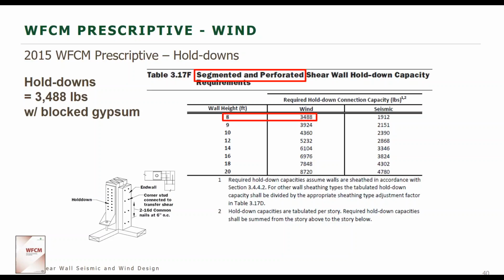It's an engineer's judgment on what they choose to use for the design of the uplift and the resistance by dead load. And if you could also distinguish between uplift at a hold down versus wind uplift on a building, and how those are resisted, and what assumptions we make on dead load in the wood frame construction manual. So the hold down is going to resist your overturning forces. The anchor bolts along the length of the wall are there to resist your in-plane uplift, along the length of the wall.